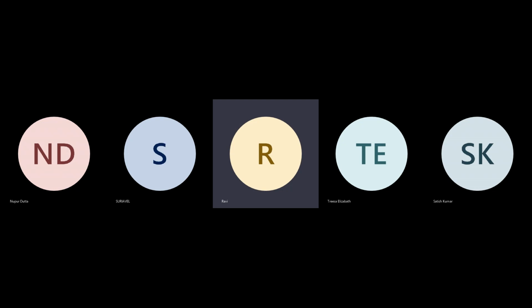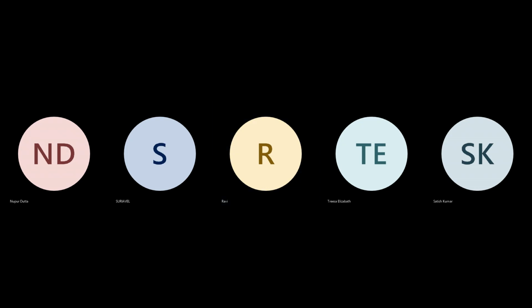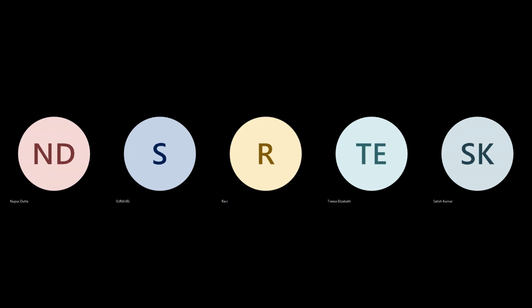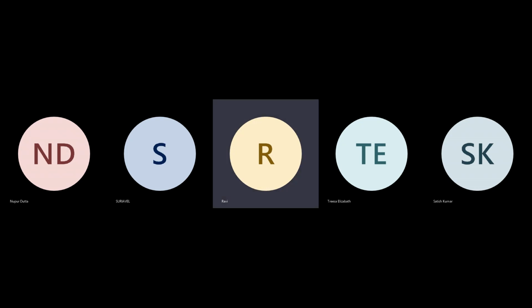Okay. So look at this module color mapping, and make sure that this particular iteration is going on, and keep track of your net length. Look at how things are progressing in your log file. In your log file, if you see that suddenly there is a utilization jump, you have to identify the step where it is happening. It will say buffering, fixing DRVs. At DRV fixing, suddenly your utilization is jumping from 60% to 74%.